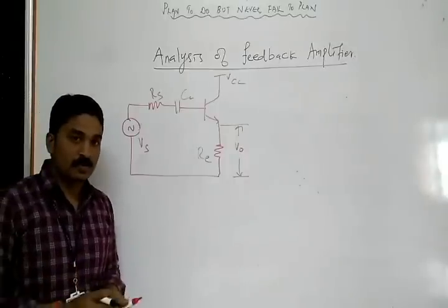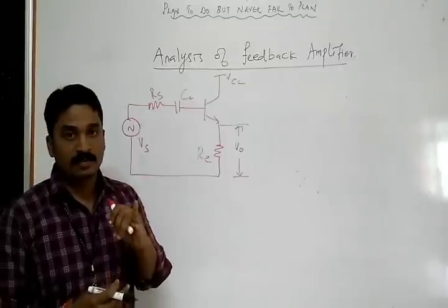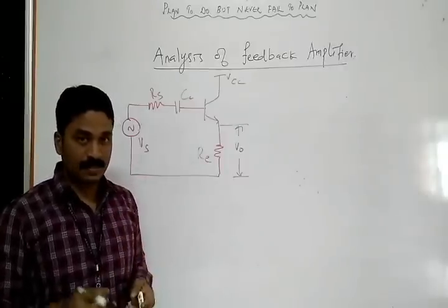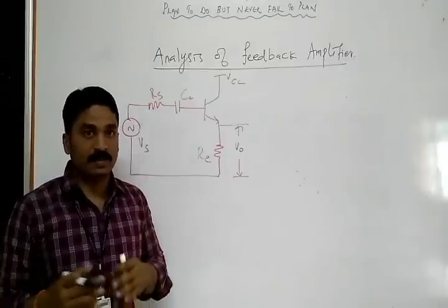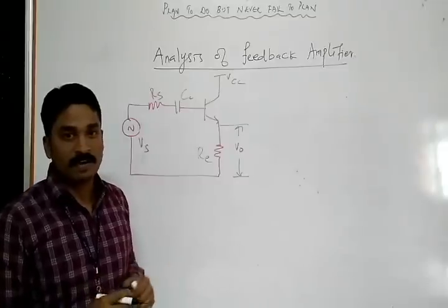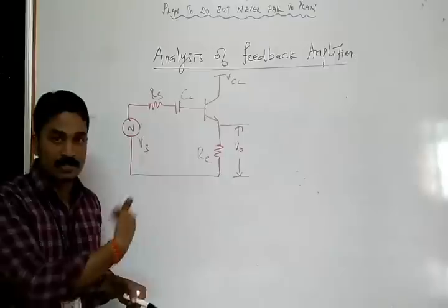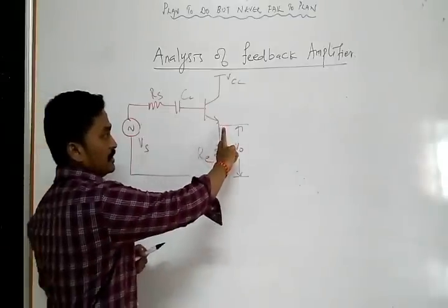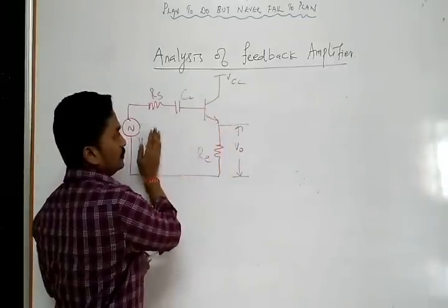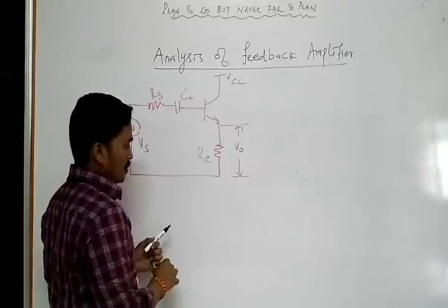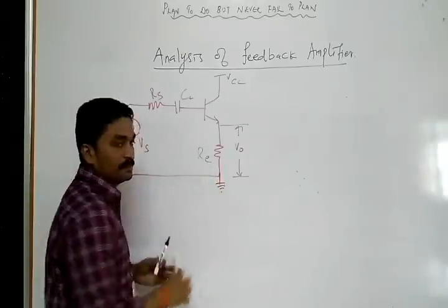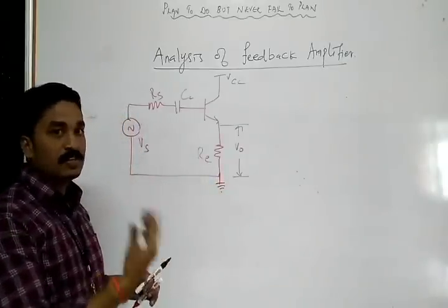According to the actual rule, first we need to find out what type of sampling. Either by using the shortcut method or the actual rule, we can find this, because we have already discussed this circuit in the previous lecture. After shorting this terminal, there will be no feedback to the input side, because through the short circuit all the current goes to the ground, which means no feedback after shorting the output terminal.